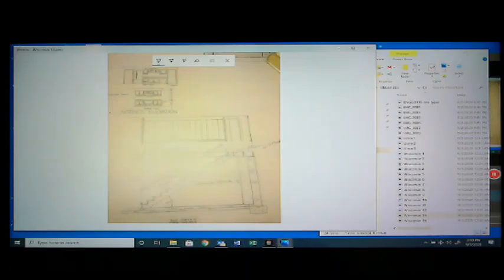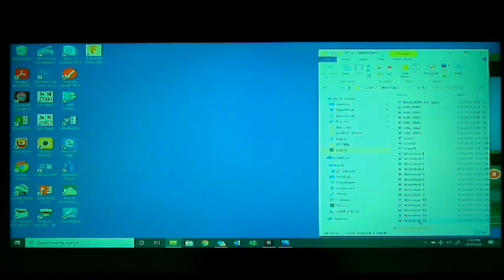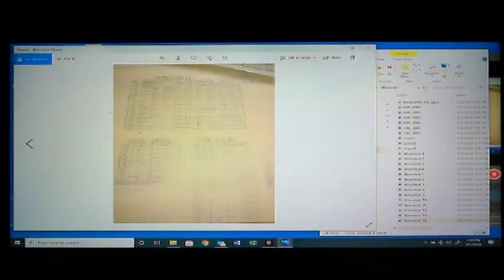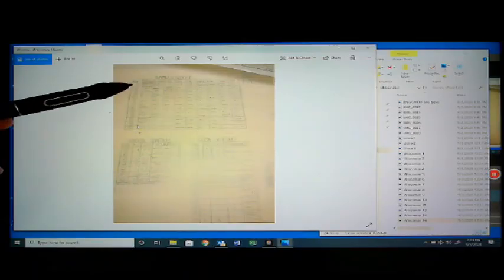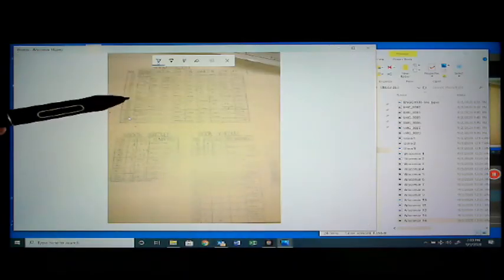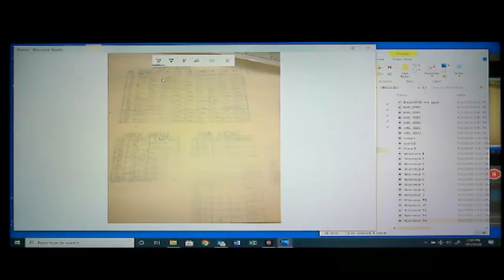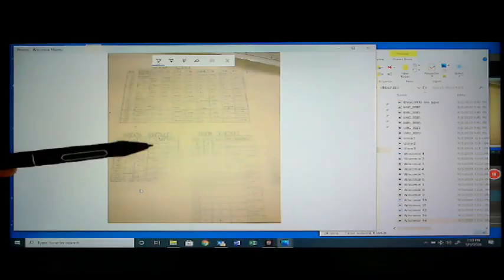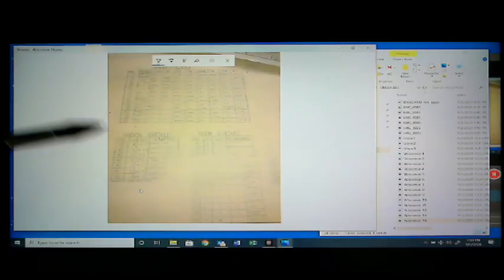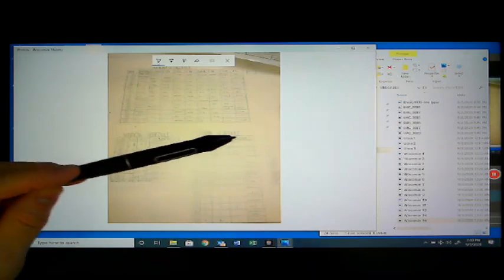All right, and one last picture. So I had to specify various details about all things that are in the room. The vault to the ceiling, the type of finish, details for every room. And you'll see there are these little circles with numbers here. That references some detail I'm trying to describe. A window schedule, so I had to pick out all the windows. So this is all the models of all the windows, all the various sizes and information, and likewise on all the doors. All the information, the schedules, so the builder can order those parts and make it happen.